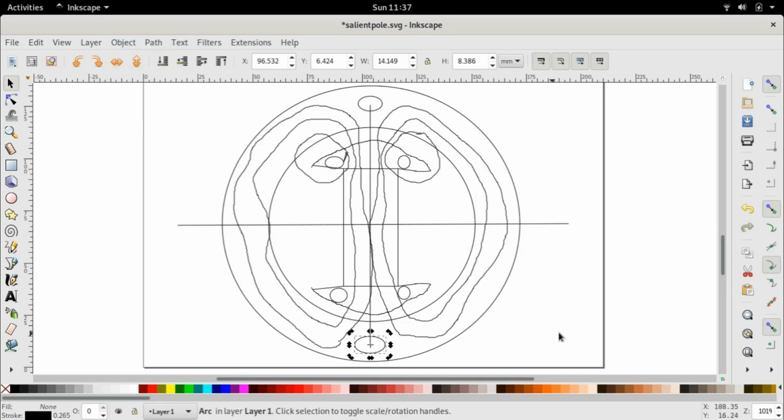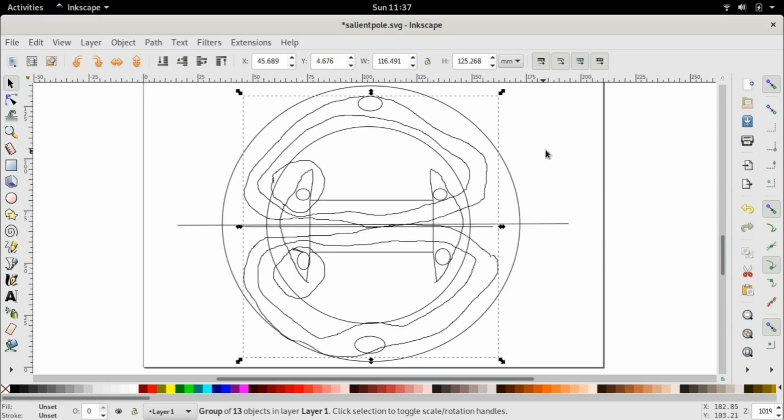These are the stator slots, that doesn't change. And now if I select it, I get the entire rotor, that is, I get the rotor along with the flux lines. The entire thing has been selected. So now, simply speaking, if I do a rotate, I have rotated this rotor by 90 degrees. Of course, you can rotate it by any angle.